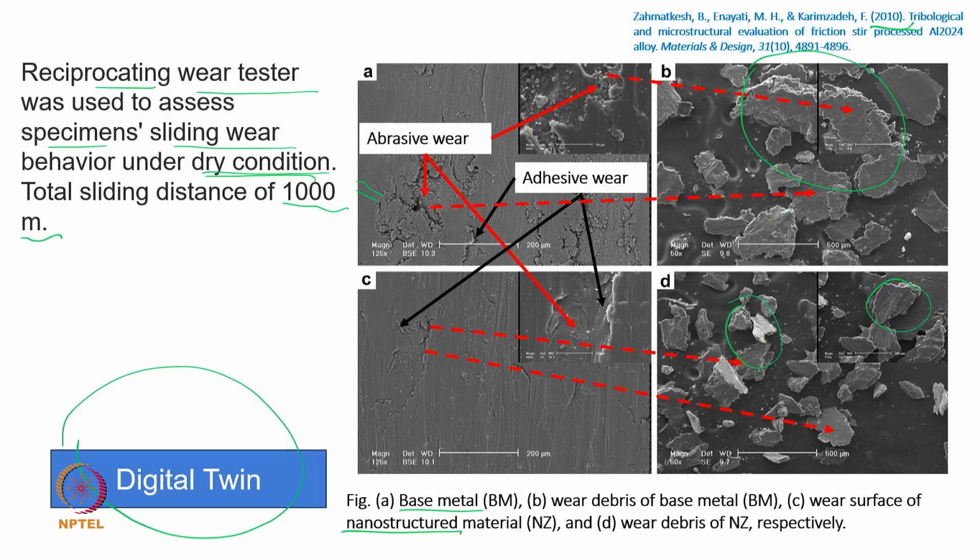Let us take a gear teeth. Now, we know the gear teeth has an involute profile, and if there is some sort of debris separation happening from a gear teeth, even at nano level, naturally the involute profile is going to change to some extent, and there is a possibility the pitting failure will increase and maybe get populated. So, why shall I go to that kind of a stage? Why not take remedial actions well in advance? That is what we are trying to think, and that is what we say the digital twin can be utilized for.